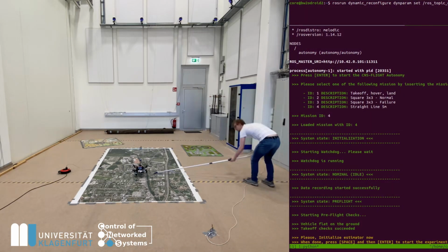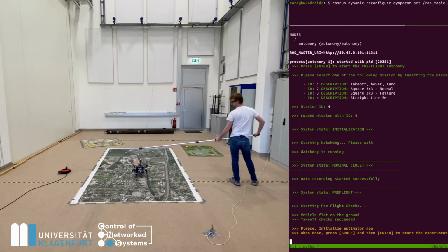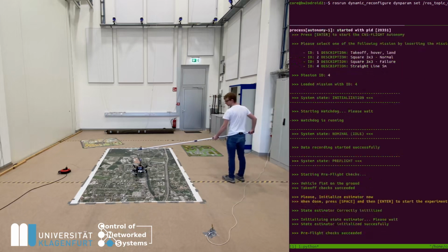This scenario shows a nominal setup in a controlled indoor environment. The setup uses the laser ranger for too-close-to-ground error and landing detection, as well as a camera for visual inertial odometry. In addition, ultra-wideband distance measurements are used for position triangulation.